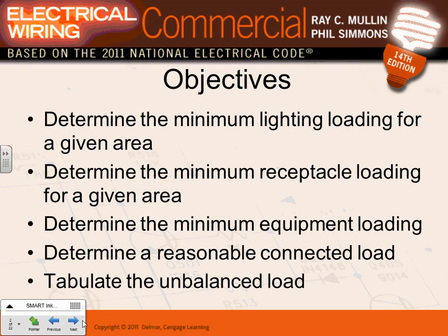Load calculation for every tenant, as well as the house panel. Okay, a couple of things, guys. You are very familiar with this one, I hope by now. Lighting loads always come in chunks. Remember that chunk of lighting loads that we did? The second chunk is going to be the receptacle loads. A third chunk is mechanical equipment loads, tabulated.